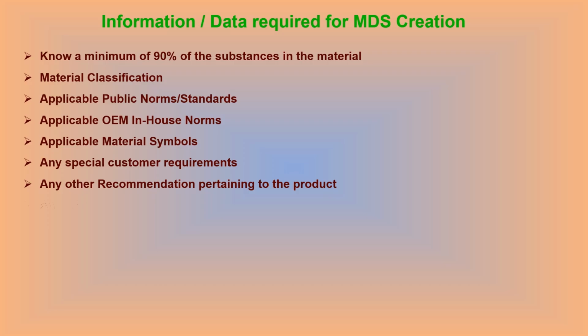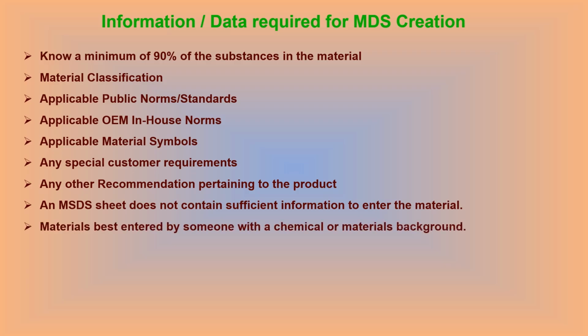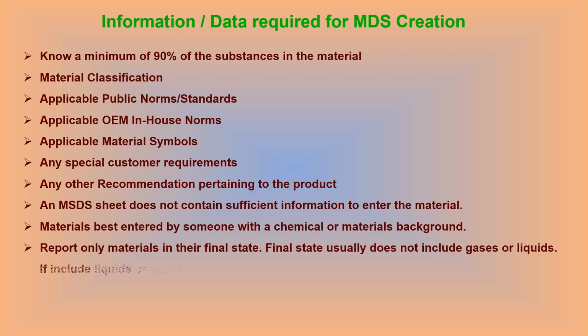Only having knowledge of an MSDS sheet is not sufficient for creating an MDS, as it does not contain sufficient information to enter the material. Material data sheets are best entered by someone with a chemical or materials background and knowledge. Report only materials in their final state. Final state usually does not include gases or liquids.